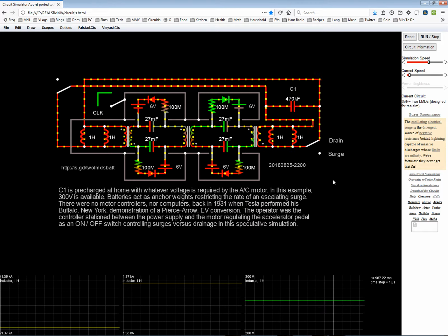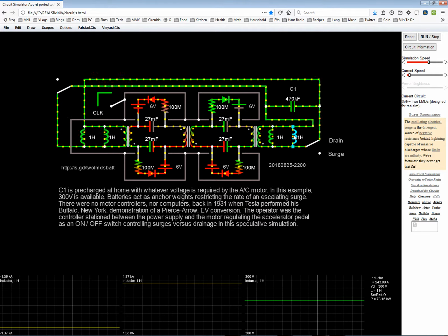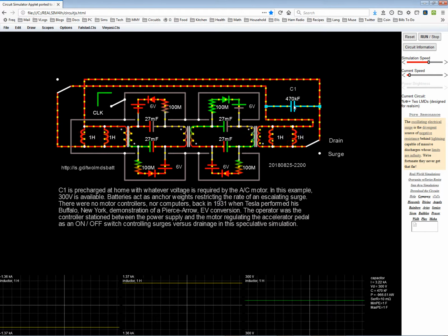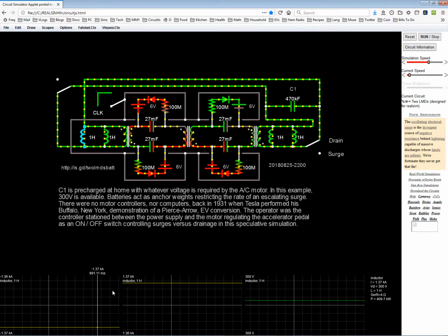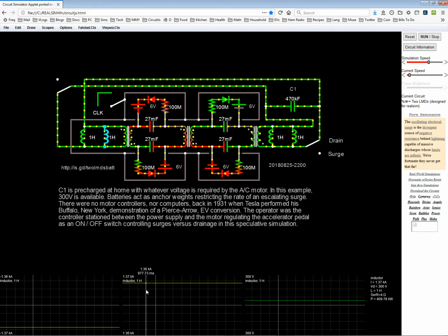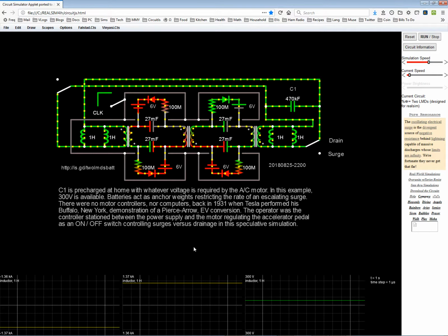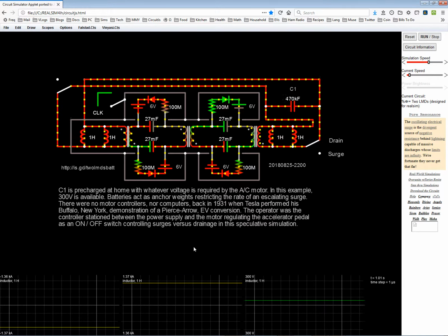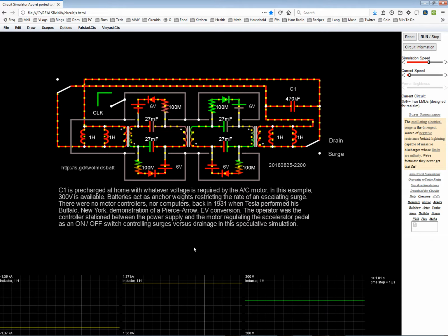Maybe a relay that flips polarity of the wiring of the coils, the motor coils, is the way to go, including this capacitor, to maintain the same sign of current at all times. Whatever works, whatever's the simplest that works, manageable, cost effective, all those things.